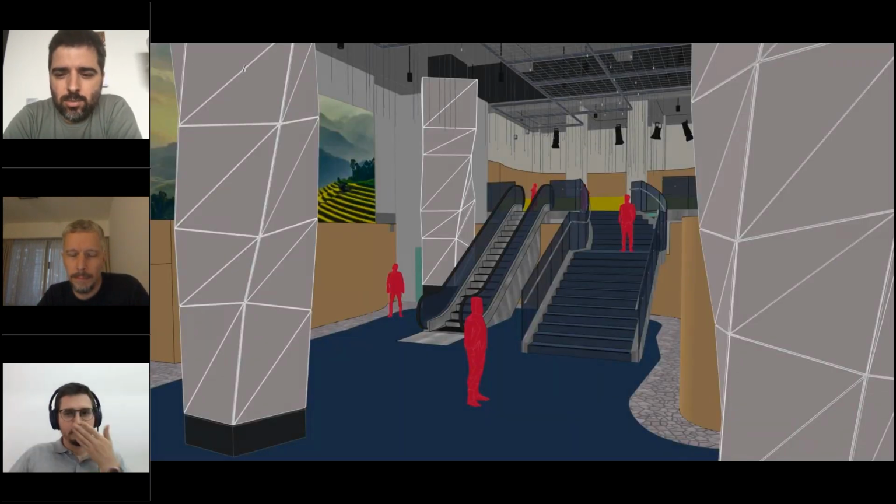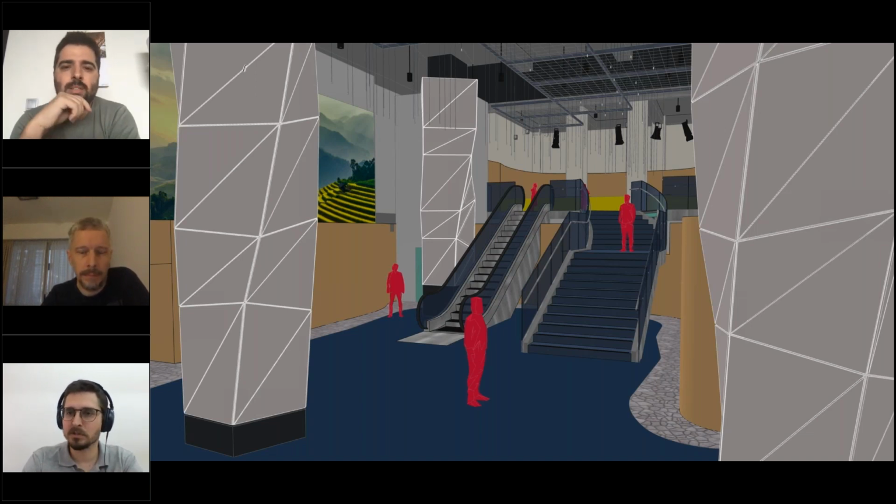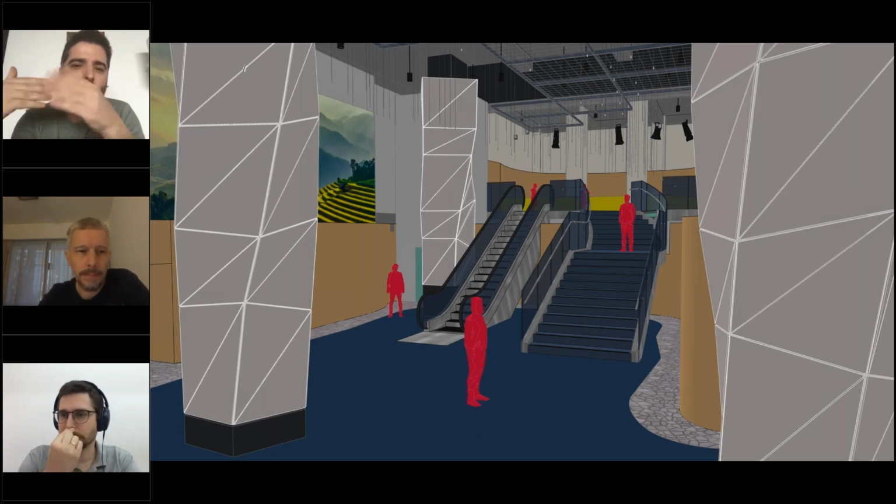I think the general question we always get here, and we have again from Jean, is how long normally does it take to load this kind of connection? And even for so many cables like we have here, every time that you have a new iteration, is there any trick that you advise to make this not hang? Yeah, I think I've said that before, but one of the first things that I usually do is to block the live link. So use a Boolean toggle and set that Boolean toggle to false in order to not send the live link to ARCHICAD, because like every time you close the door, only when you decide to open the door, the information will flow.